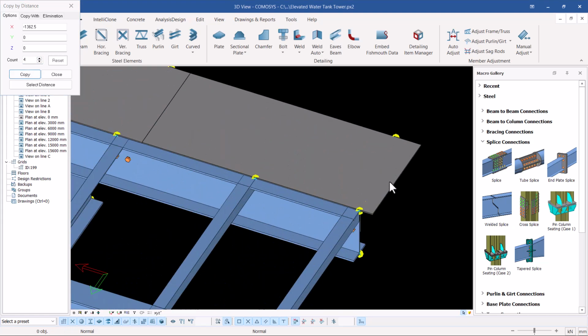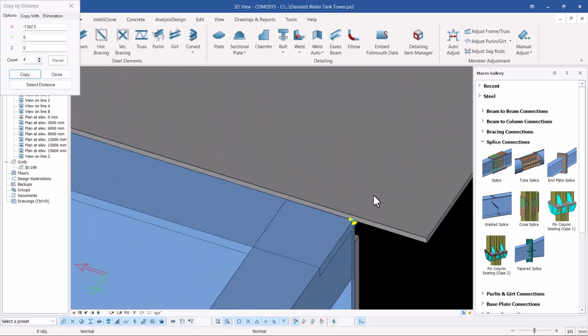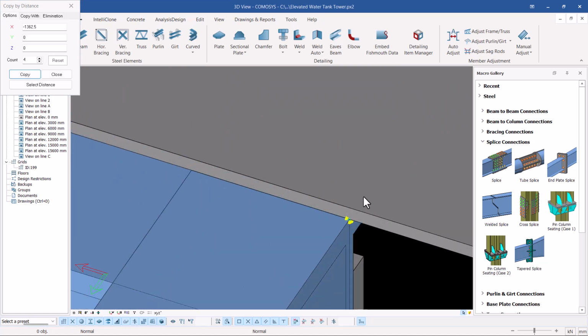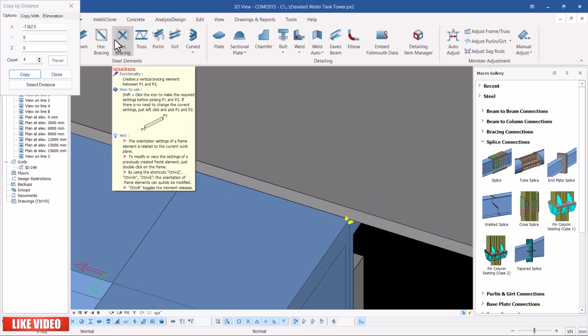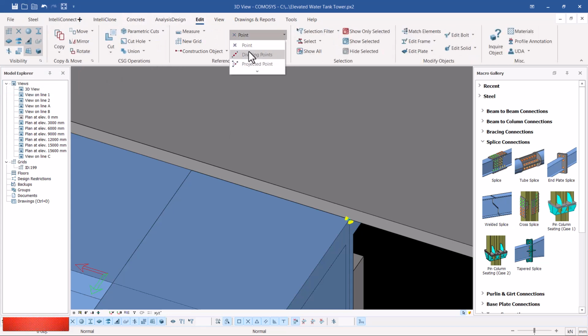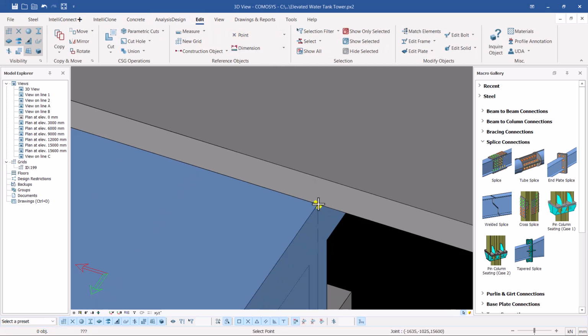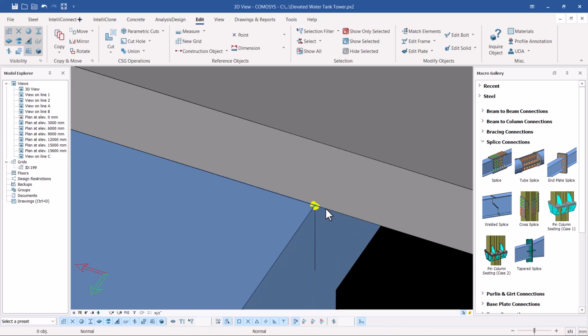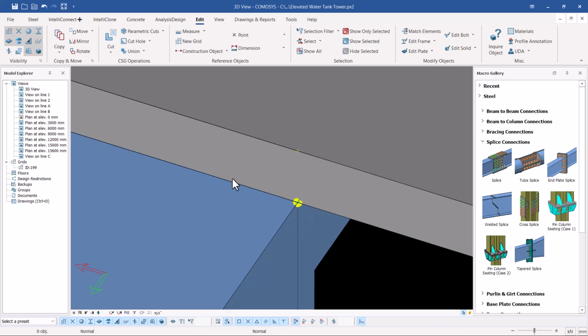So we have our checker plate in place, but there's a slight extension outward. So what I'm going to do, we'll just cut that off by using cut polygon. So I'll come to edit, I'll come to point and pick on point here. I'll snap on the bottom end here and snap on top here. I'm not able to get that point accurately, but let me just transfer that point upward. So I'll come to project point and press Ctrl and snap on any point here. Then I'll select on that point at the bottom end there and project that point upward here.